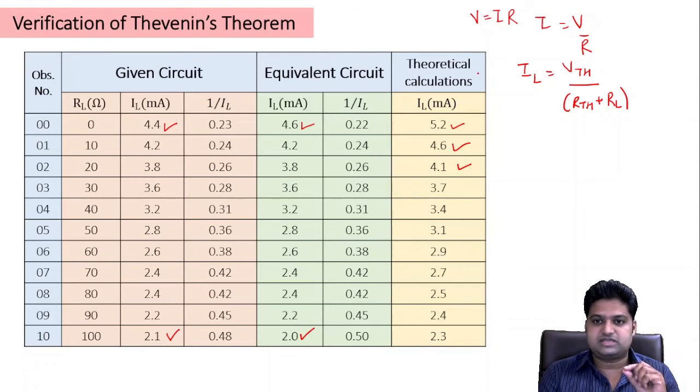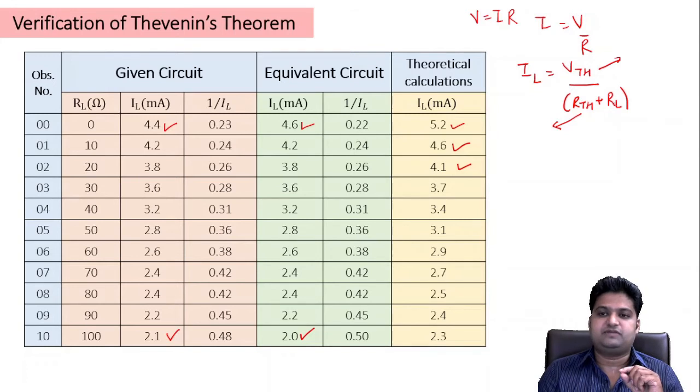So these calculations that we did using this formula, just varying RL every time. You can also do VTH. You remember what it is. We have done the calculation for VTH, and you remember what the RTH value was, right? RTH was 75 ohms and VTH was 0.393. So if you just put different values of RL, you will get these calculated values.